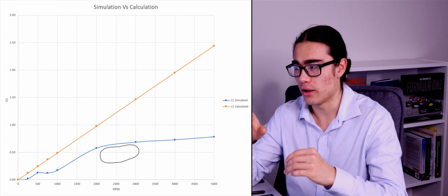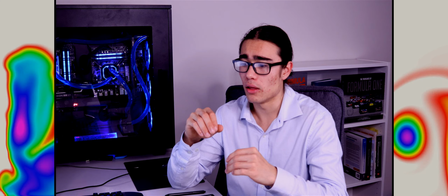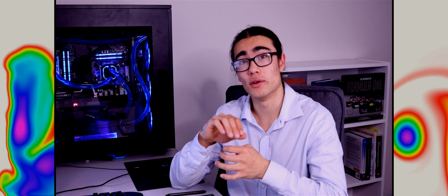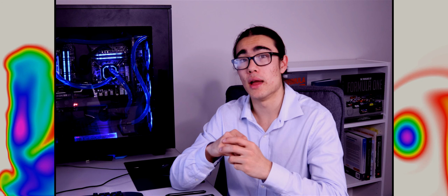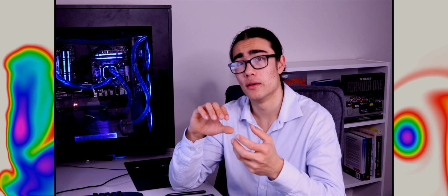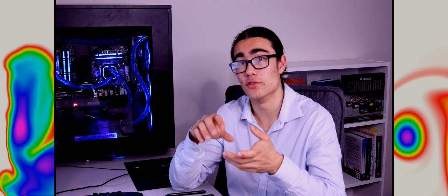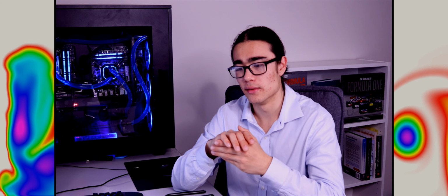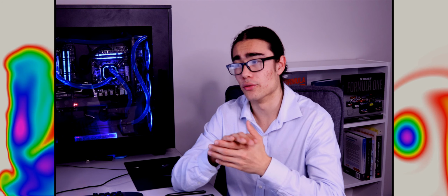So the general takeaway is, no, I don't think it's a linear relationship at all. Now, if you're actually going to apply Magnus effect to a real application, there's a lot of other things you're going to need to consider. Firstly, what's the geometry like? Is it a perfectly round ball, or after you hit it, is there deformation? Are there creases in the ball, or is it smooth all the way around? Are there roughness changes throughout the match, for example? The other thing to note is Reynolds number, which is very important, as we'll discuss a little bit later on.